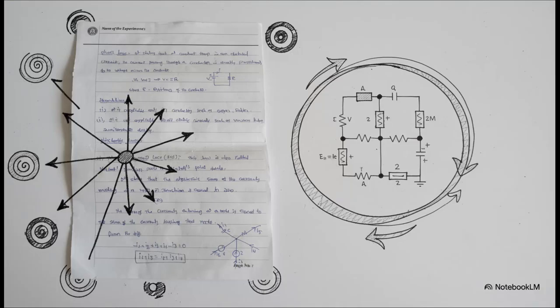What's really fascinating here is seeing KCL placed right side by side with its sibling, KVL, Kirchhoff's voltage law. Over on the left, from the handwritten notes, you see the KCL point rule. If you track the arrows, currents I1 and I5 are heading in, while I2, I3, and I4 are heading out. They balance out perfectly. Then on the right, we've got the KVL loop rule, which applies a very similar logic but to voltage around a closed circuit loop. The total voltage supplied, minus the voltage drops across the resistors, will always equal 0. When you put them together, the point rule for current and the loop rule for voltage basically give you total mastery over analyzing any basic circuit out there.